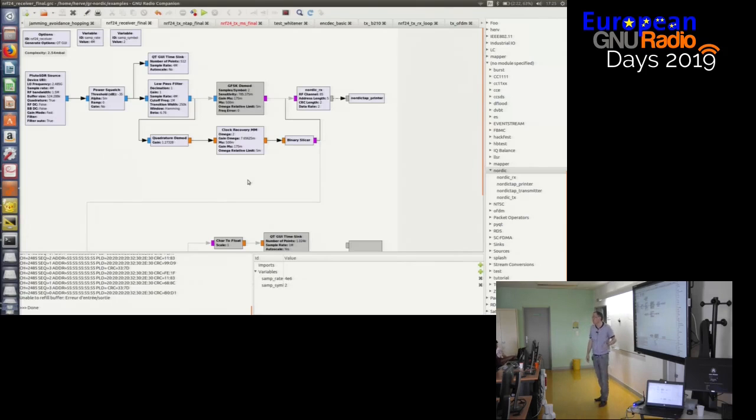But the preamble and the address are both 0x55. So if you have a distortion in the beginning, then you might see part of the address as the preamble. Correct. Sometimes it doesn't work. It's possible. That's why, you know, using sequences like that, sending the packet several times, or using something a bit more sophisticated.